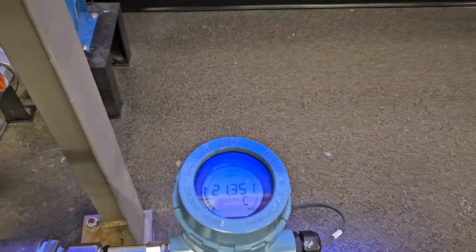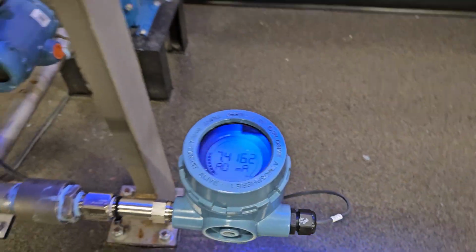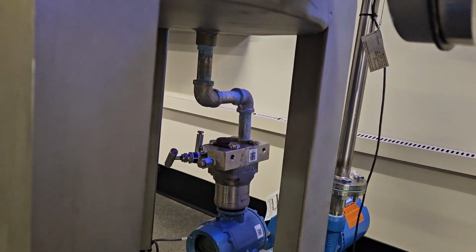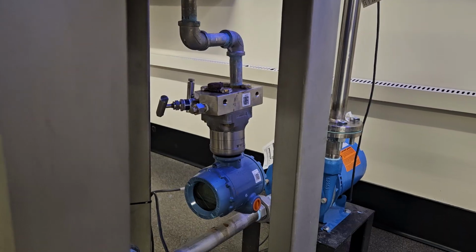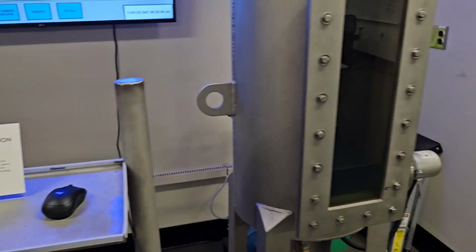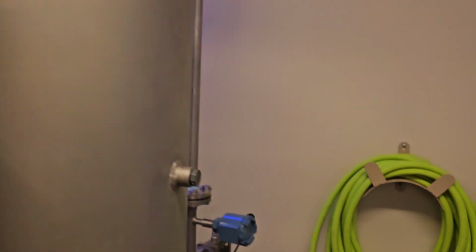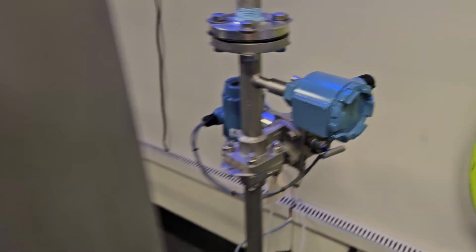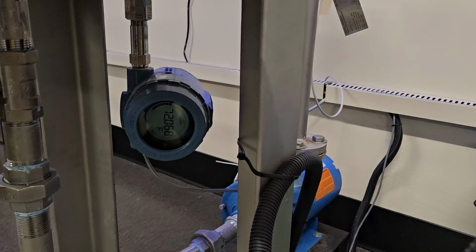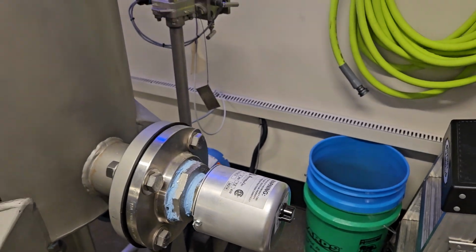We have a temperature sensor here, reading 21.3 degrees C. We have a differential pressure level sensor here, an instrument where we're comparing atmospheric pressure to the tank pressure. We have a contact radar level here with that rod that's sticking down. You can kind of see it there, that silver rod in the background. That's actually contacting the water. Another discrete fork level, another DP flow over here, and a DP flow over there. And then we also have another temperature sensor over here, and we have a heater on both tanks.